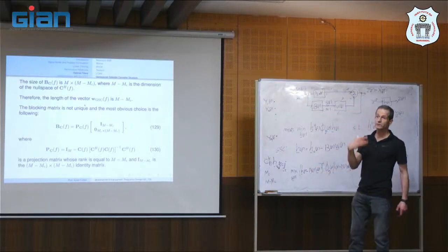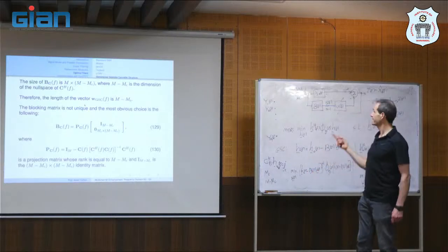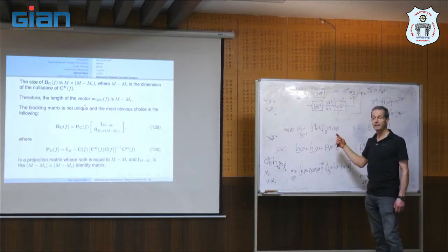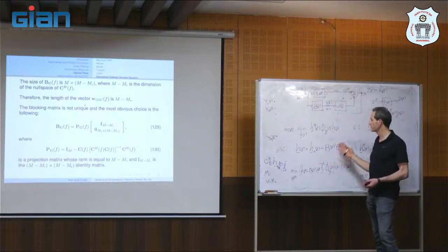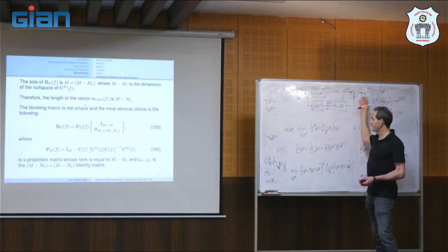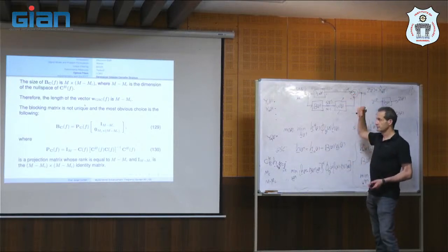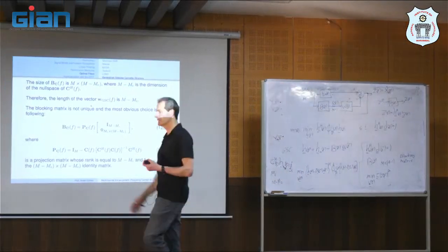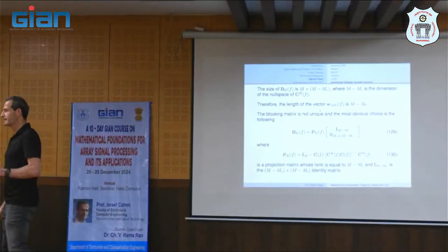So it's unconstrained minimization, which is much simpler. It's just like adaptive filtering. We can do it offline, but there is no advantage of doing offline, because if we do offline, we can find a solution of the LCMV. But we can do it online with adaptive filtering. So it gives us the flexibility of implementing LCMV with adaptive filtering.